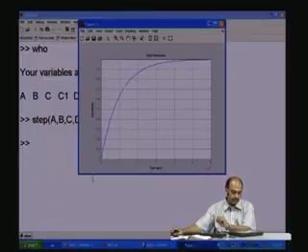You see, this is the step, this is the unit step 0 to 1, and you see that the waveform, the output is rising in this fashion towards 1. So, you have the amplitude, the time, you have the grid, you can read off what this is about 6 milliseconds, 6 in 10 to the power of minus 3. So, you can read off the rise time, that is around 90%, something like 2 to 2.5 milliseconds for this particular thing.